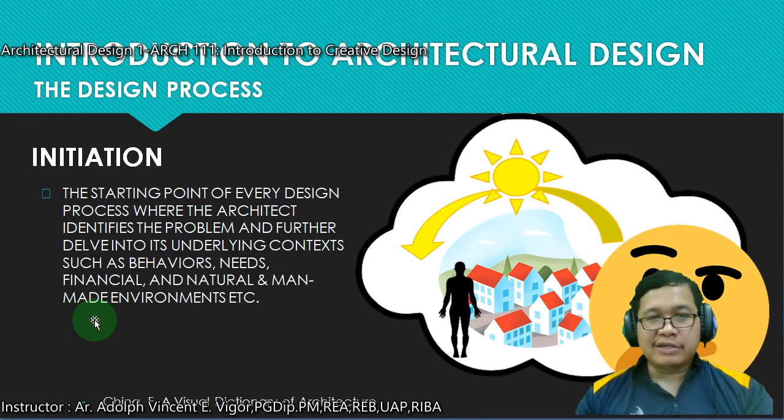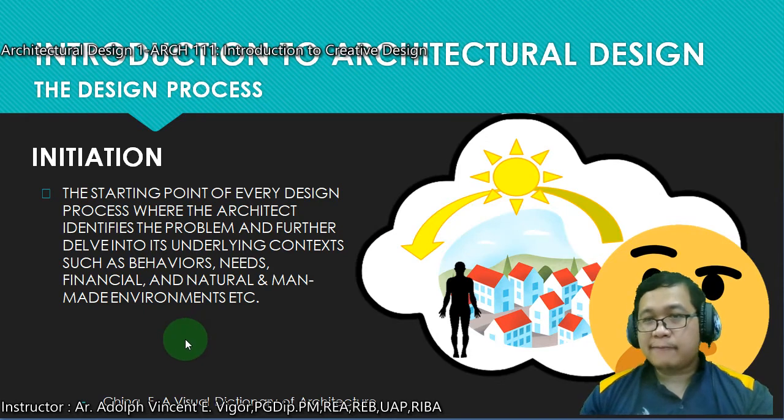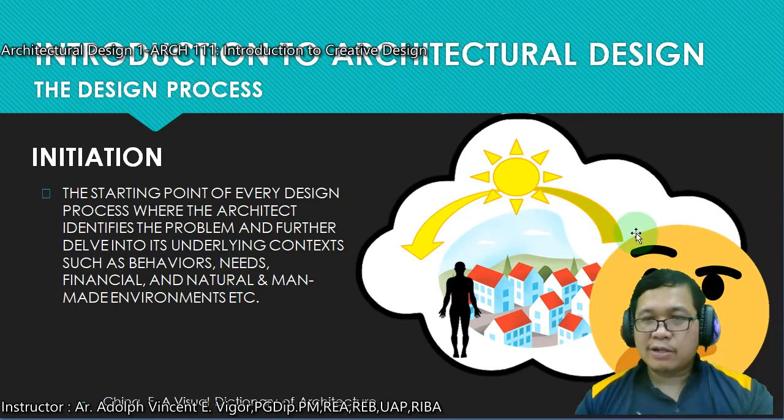Okay, now let's begin with initiation. So it is the starting point of a design process where the architect identifies the problem and further develops it into its other contexts: behaviors, needs, financial, natural, and man-made environment. So this is the phase where you're going to identify the behavior of the users who will be utilizing the building, then how much their budget will be for that structure, then what is the surrounding natural and man-made context within the vicinity where the project will be located. Okay. And as such, in the initiation process, you have to understand where the sun will pass through the property so that you're able to orient the faces at the right angles or arrange them in accordance with that data. Okay, so this is a stage wherein you're going to determine where the wind will pass by so that you can have extra cooling for your structure. Okay, that's the process of initiation.